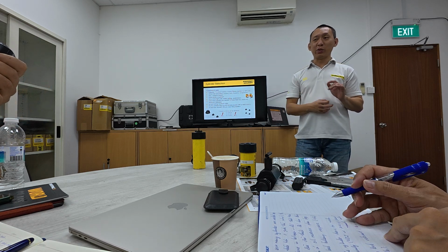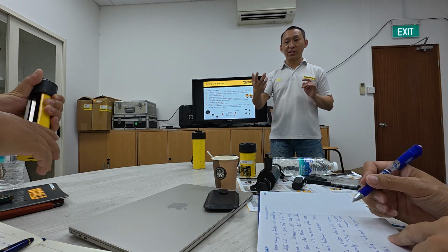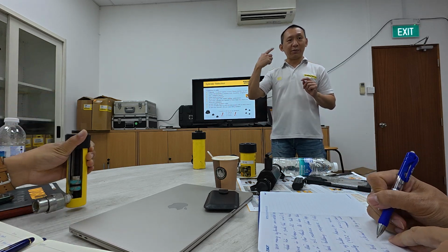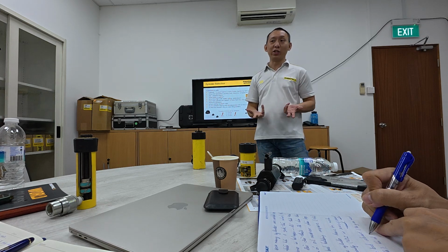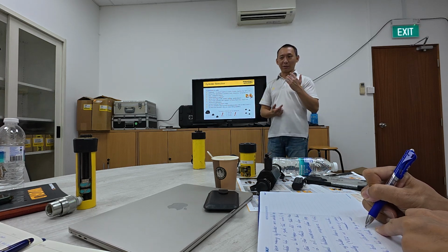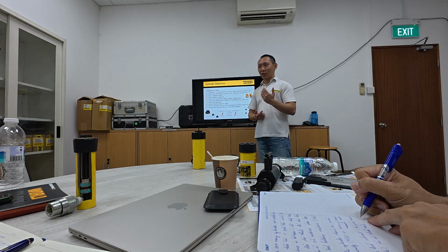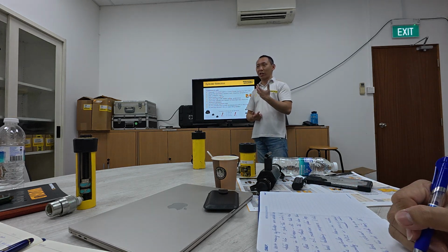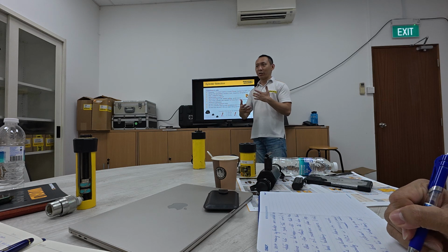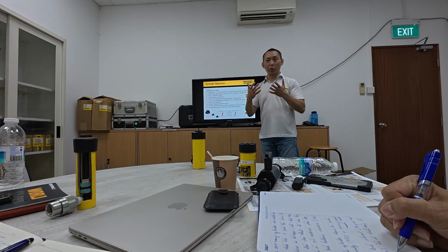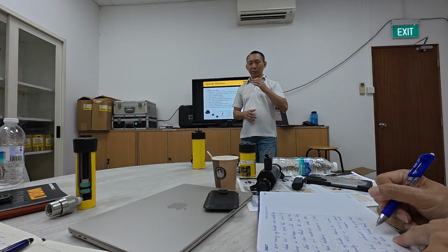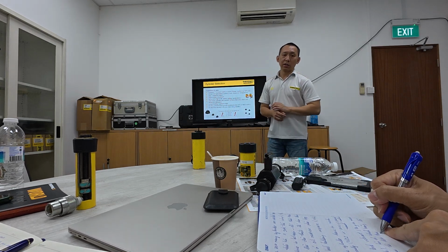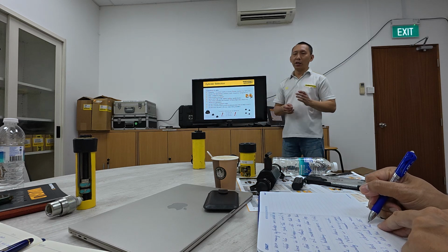And then the thing is, even if you give a replacement cylinder, the chances of a customer making the same mistake again is very high, because the customer doesn't understand what side load is. So sometimes it's not always about goodwill to the customer, because the customer will not be educated to use the tool properly. Sometimes we have to hold our stance. Otherwise you will run into a problem.